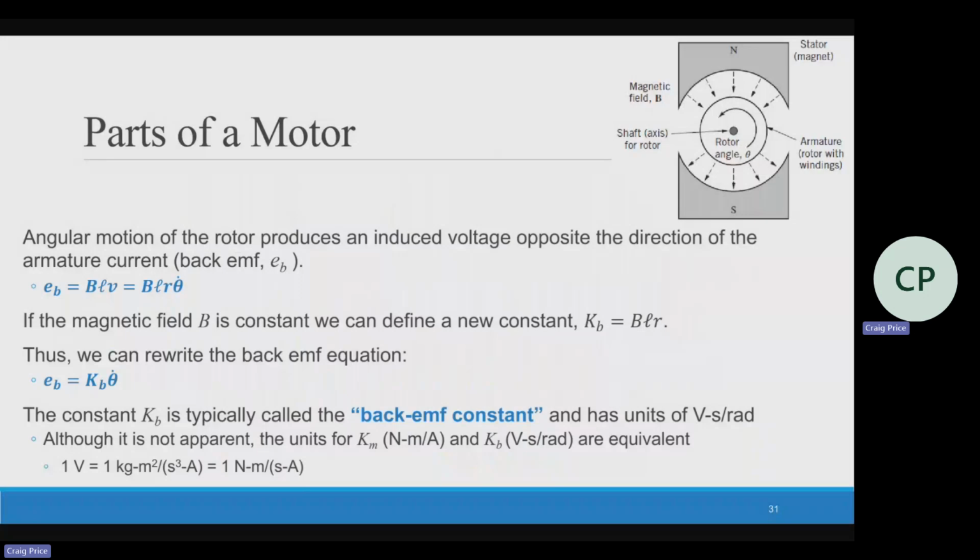In a practical motor, the armature loops are fitted inside slots of highly permeable steel layers. This will enhance magnetic flux interaction. Spring-loaded commutator brushes help maintain contact with the power source. A permanent magnet stator pole is used only for very small DC motors. Most often, an electromagnet is used. The field coil of the electromagnet is powered from the same DC source.